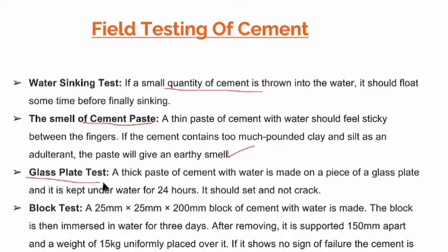Glass plate test. A thick paste of cement with water is made on a piece of glass plate and kept under water for 24 hours. The cement paste should set and it should not crack.